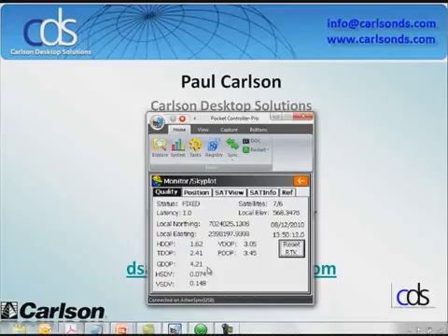Now, if you're using an older version of SurvCE, this is going to look different. In the previous versions of SurvCE, this was registered as horizontal and vertical RMS values, the horizontal and vertical residual values. Now we're looking at standard deviations, SDV, horizontal standard deviation and vertical standard deviation. Okay, a change in terminology is simply what we're looking at. But I know the first time I saw it, I panicked because I didn't know if I had unchecked something that's supposed to be there.